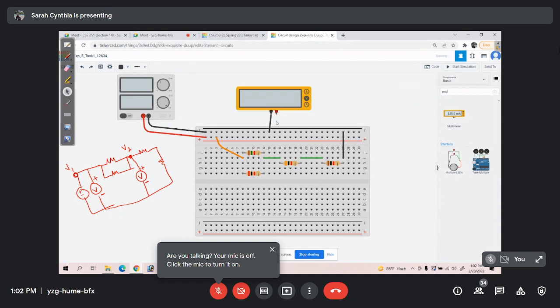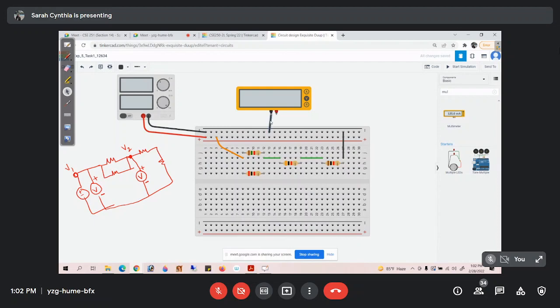So let us use this same voltmeter, but the wirings would be different. Since it has the same negative terminal, I'm not changing the negative terminal's wire. I'm keeping it as it is. However, the positive terminal of the multimeter will be connected to this particular node. Now, where is this node in my circuit?